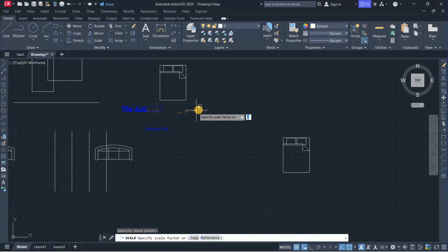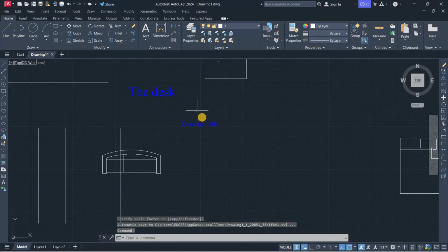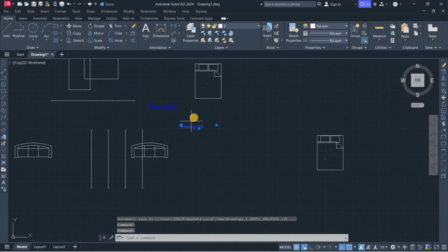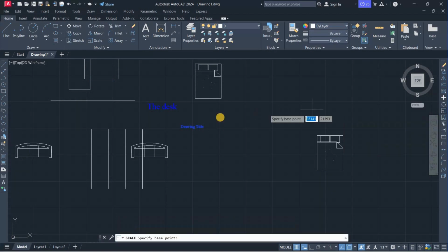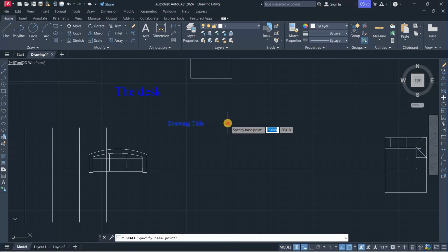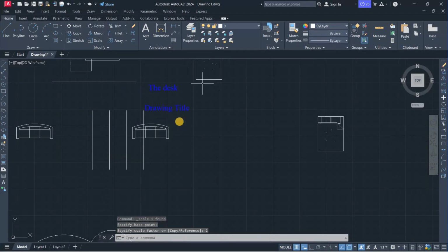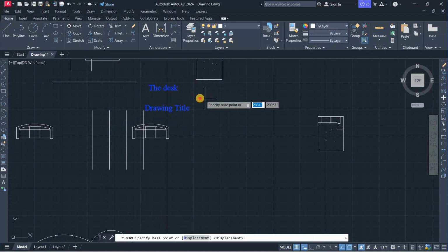Of course, after that, you can click when you're comfortable with that scaling. You can also select it and then specify a scale. So after hitting the scale tool, I specify a base point. Of course, I want to double the size, so I can simply type 2 and hit enter. So that doubles the size of it. Let's move this out here.